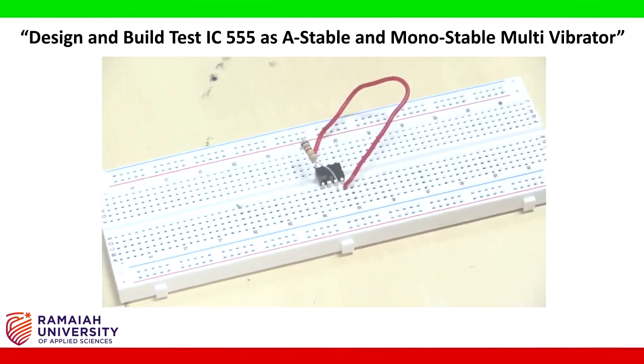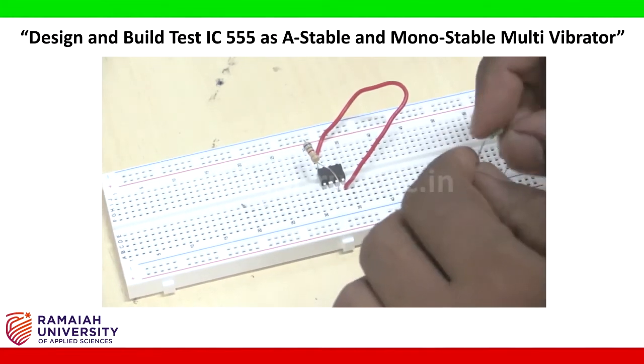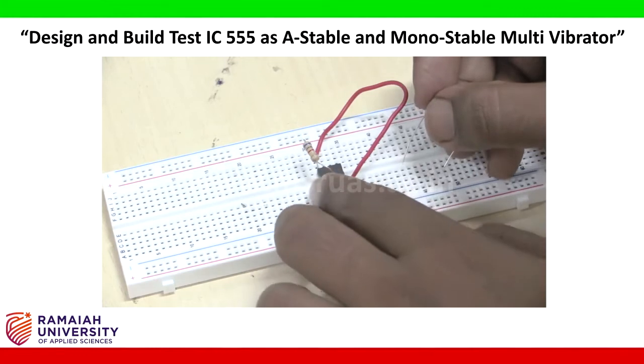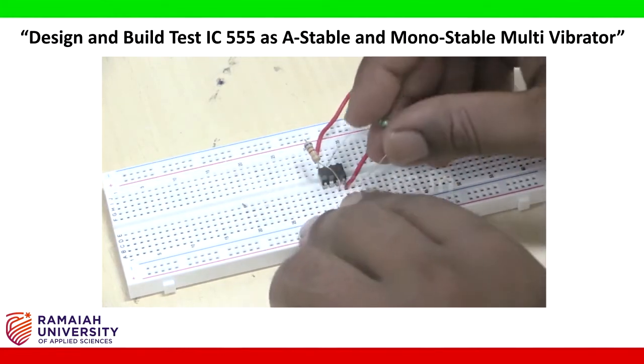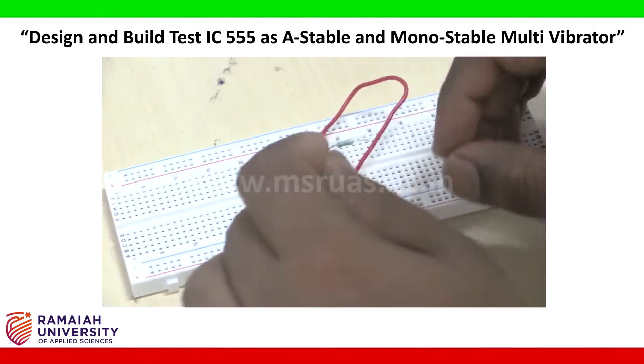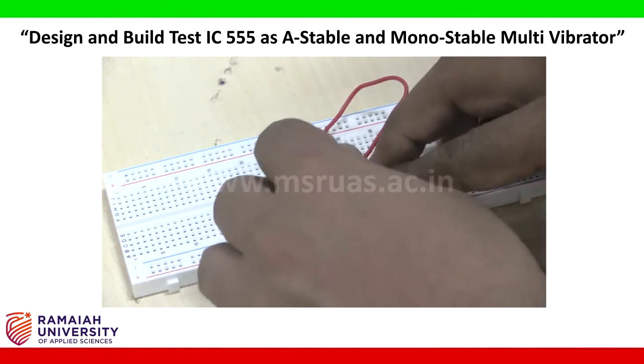Next I need to connect a 3.6 kilo ohm resistor in between pin number 7 and pin number 6. Pin number 7 and pin number 6 are this one, 4, 5, 6. This is pin number 6 and this is pin number 7. In between these two I need to connect one 3.6 kilo ohm resistor.